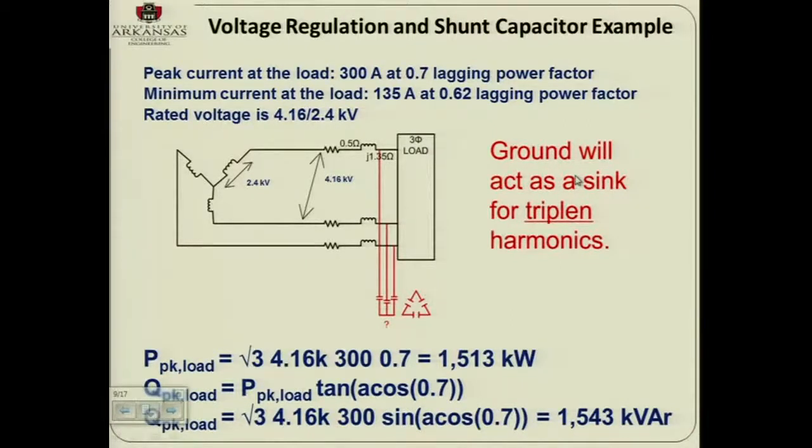Heat. Correct. Losses, power losses. Any current produces losses, whether it is your smart iPhone, your electric motor, or an electric car. Current produces heat: I squared R. And if it's three-phase, you multiply by 3.